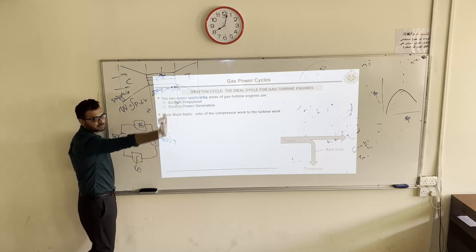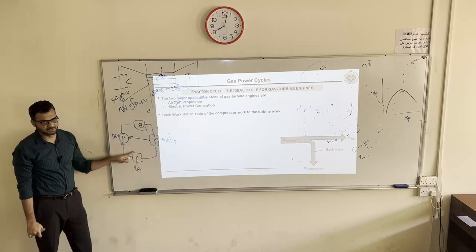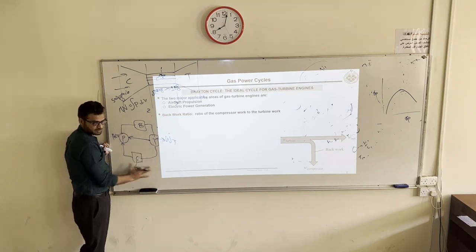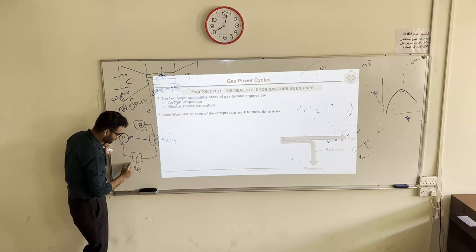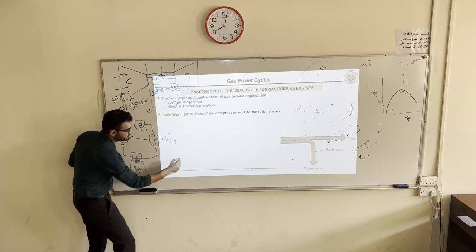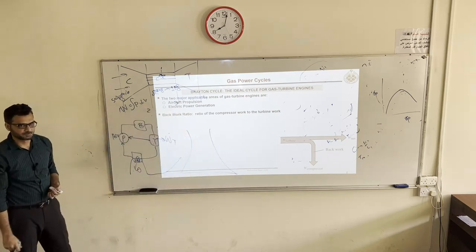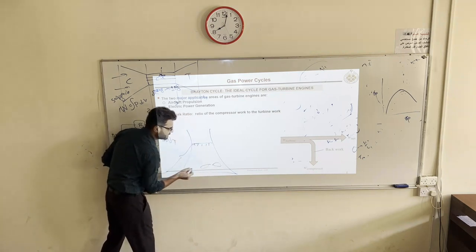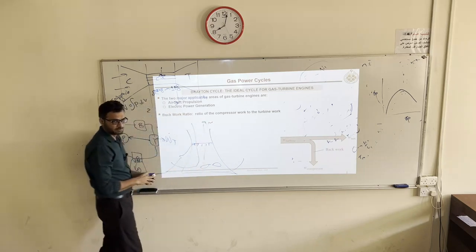But here you do not have any condenser, just air entering and leaving. There you have a huge condenser, a cooling mechanism. So the initial cost is much larger there because this is a huge component. It's not just a simple condenser. There you have cooling water. This cooling water is going where? Have you seen such cooling towers? You would have seen such cooling towers. So this water is going here. Here you have fans. It is taking the normal air. That is called evaporative cooling going on.